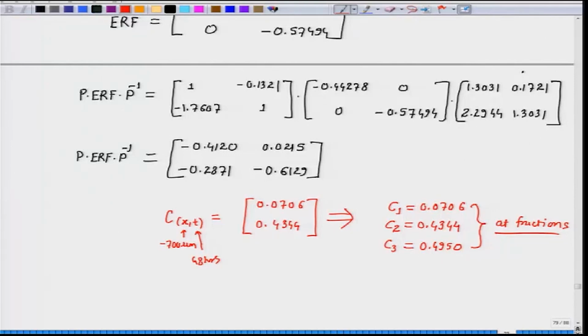x and t in any multi-component diffusion couple. Again, we illustrated this with a ternary diffusion couple, but similar procedure you can apply to quaternary, quinary or higher order diffusion couples. Okay. We assumed the interdiffusivity matrix is constant throughout the diffusion zone, and also molar volume was assumed constant. So, we can use, instead of moles per centimeter cube, we can also use the atom fraction or even weight fraction, because molar volume is constant, it is independent of composition.